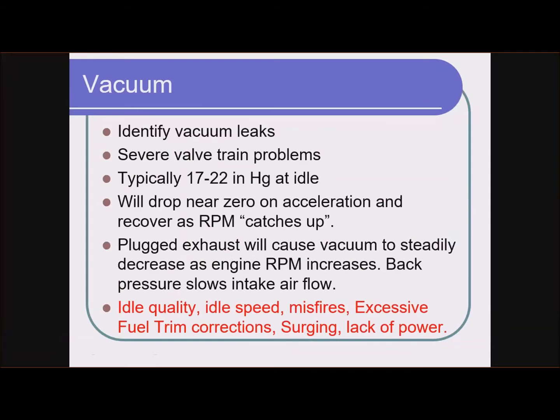Some of you, I'm not sure if you all got to see in lab before we got kicked out, I had a back pressure gauge, and we removed an oxygen sensor and screwed this gauge in its place. I know some of you saw it. I can't remember if you all did. So that's another key that we can look at.